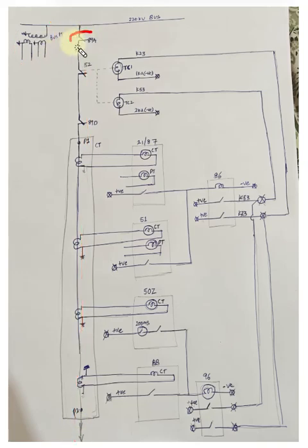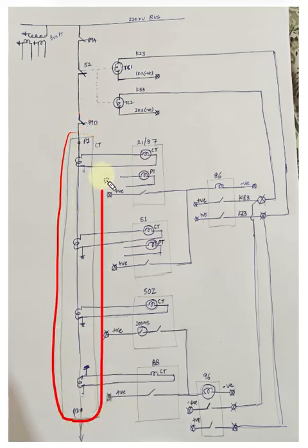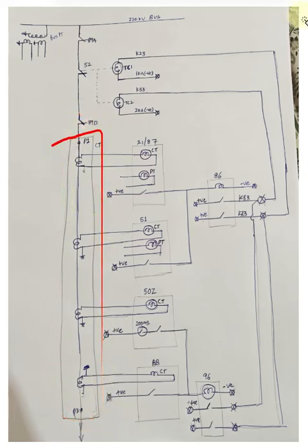Okay, so first thing here is the bus isolator, then there is a breaker. All right, after the breaker there is a line isolator, and then there's this CT. The CT has 5 cores. First one is used for main protection, then second one is for backup protection, third is for metering that we have not shown here, then one is for LBB, and then the last one is for the bus bar protection.